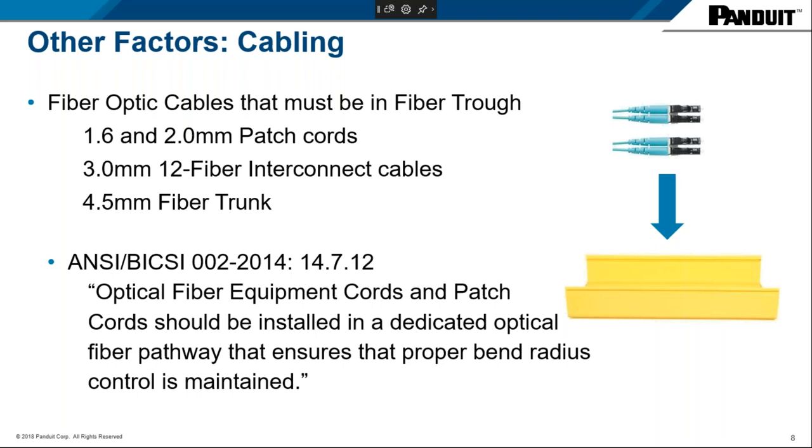So again, just highlighting some of the critical aspects if you want to maximize the long-term performance of the cable. There are specifications out there that focus on having a dedicated optical pathway for your fiber cable, and it ensures that it promotes proper bend radius control. Again, just highlighting the need of following proper bend radius control and protecting that cable.